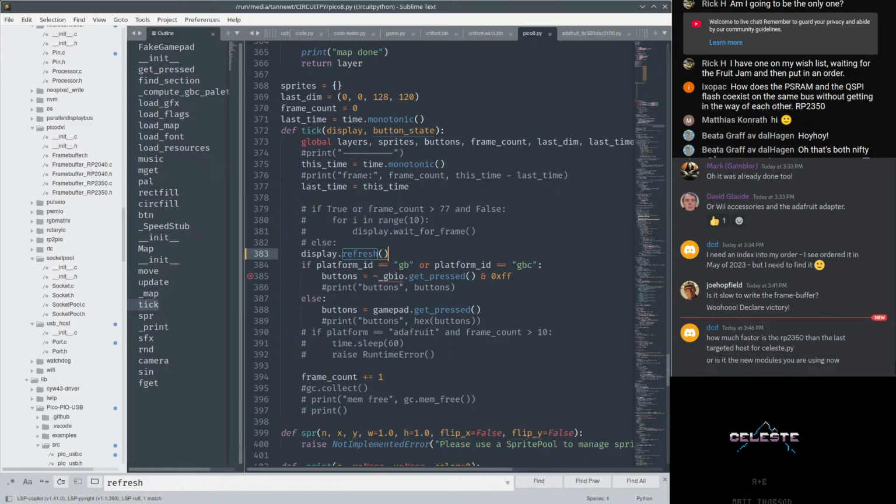By knocking the resolution down, going to pixel doubling, we're doing half the memory transactions that we did. If we do full, yeah. HSTX is consuming lines of the frame buffer pretty much continuously.